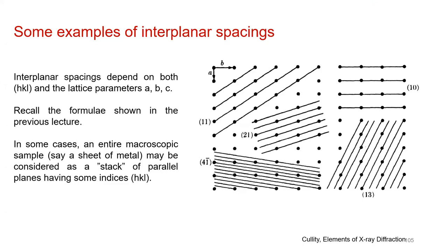Right. So, what we discussed yesterday, we looked at the packing of close packed planes, and we saw how we could actually generate the closest packed structures like face-centered cubic and hexagonal close packed, starting from a linear array of closest packed atoms. Then we built up a 2D layer which is close packed. Then we saw how we stack those two layers on top of each other to get a 3D kind of structure. So that is what we discussed yesterday.